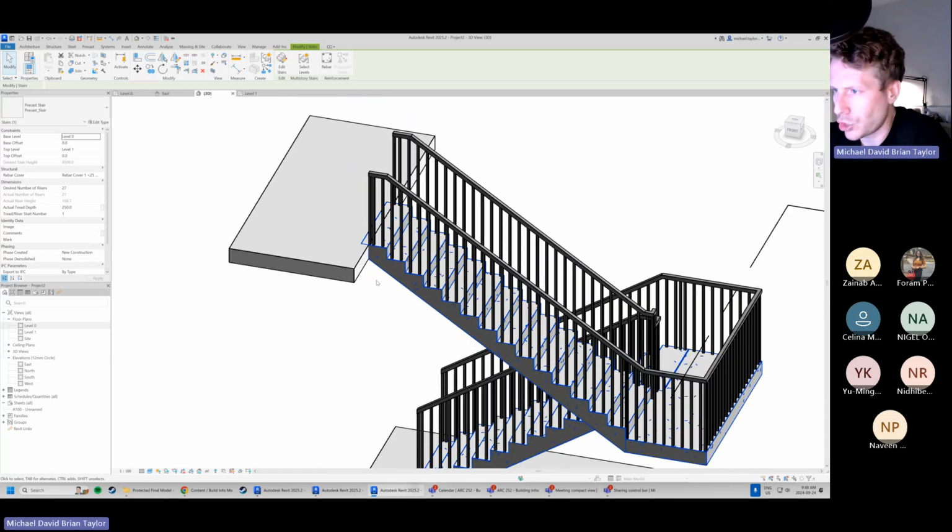So that little notch, it's hard to see, but that little notch there is meant to tie into the overall structure of our floor. In this case, we've got a little concrete floor and we've got a precast stair, and they notch out the concrete and have a little support for our precast stair. Again, this is a very standard stair. It's not too much going on. In a future tutorial, I can do a version where we've got a slightly more complicated stair, and I'll show you what that looks like.